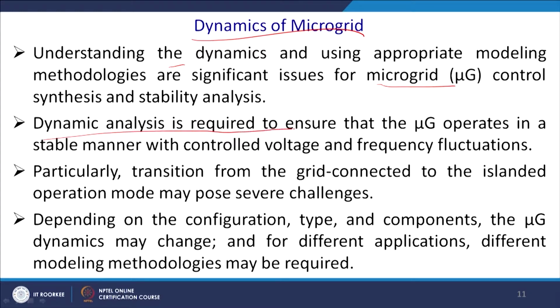Dynamic analysis is required to ensure that the microgrid operates in a stable manner with controlled voltage and frequency fluctuations for interaction with the AC/DC microgrid or hybrid microgrid. Particularly, transitions from grid connected to islanding operations may pose several challenges. That is something we require to address also.